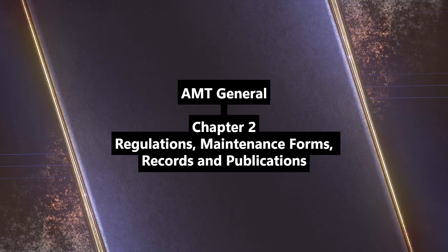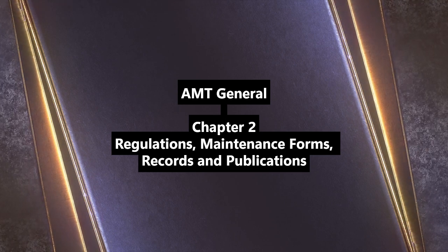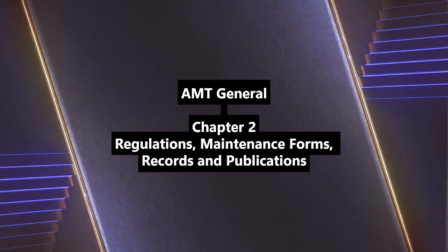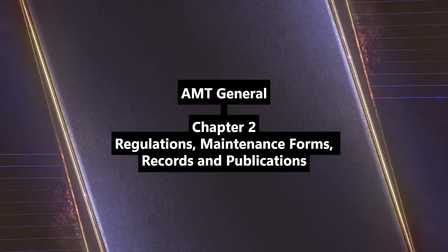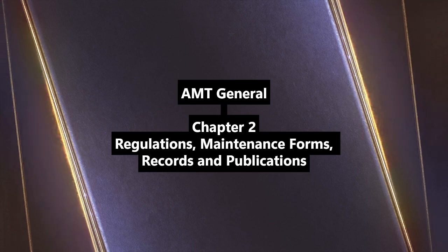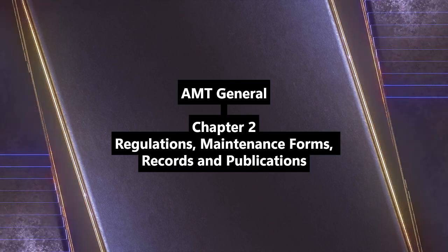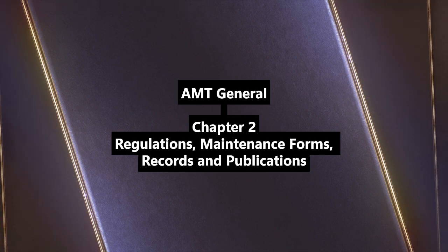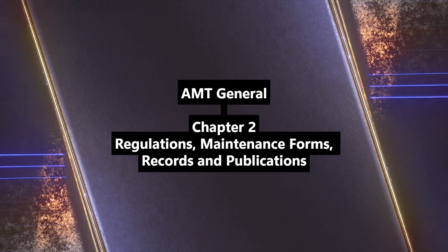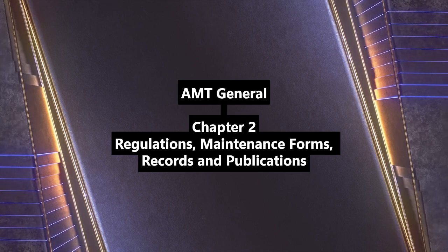Minimum 2 copies; the owner gets the original. The FAA in Oklahoma City gets a copy within 48 hours of return to service. It used to go to the FSDO first, but that changed. And the repair station exception. Right. Part 145 stations can use a signed work order maintenance release instead of Form 337 for major repairs. Also, a third copy of the 337 must be in the aircraft for ferry tanks in the cabin cargo area.